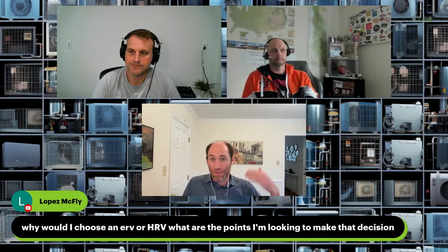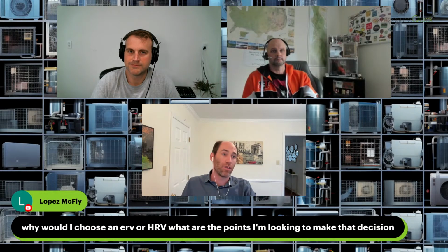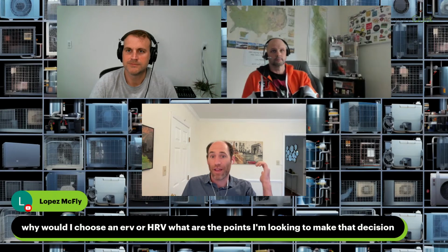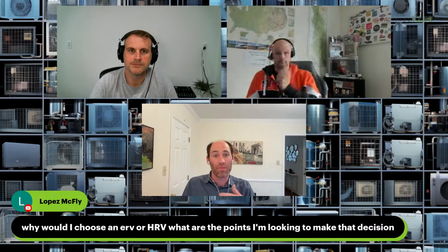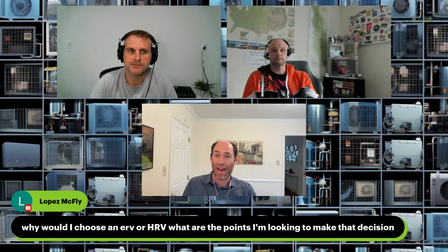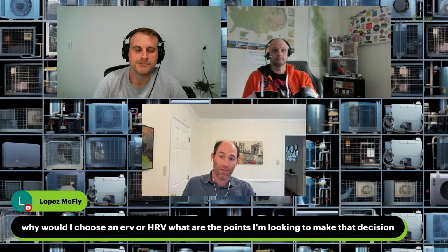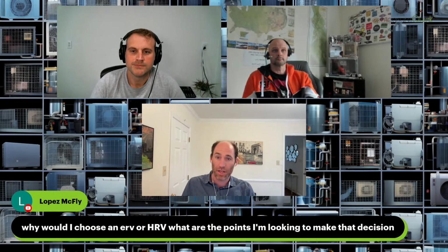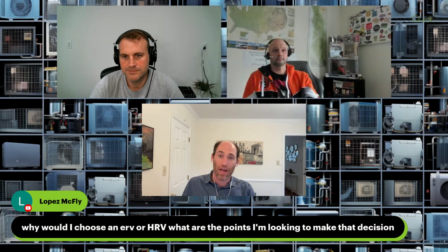If I've dehumidified my air and it's very hot and humid outside, when I bring in fresh air, I get to dump a good portion, up to half of that heat and humidity, into the stale air going out. So when it comes in, it's not that hot, it's not that humid. And that made a big difference on this project. That cut 10 gallons of water a day coming in to about 5 gallons of water a day coming in through the ventilation system.